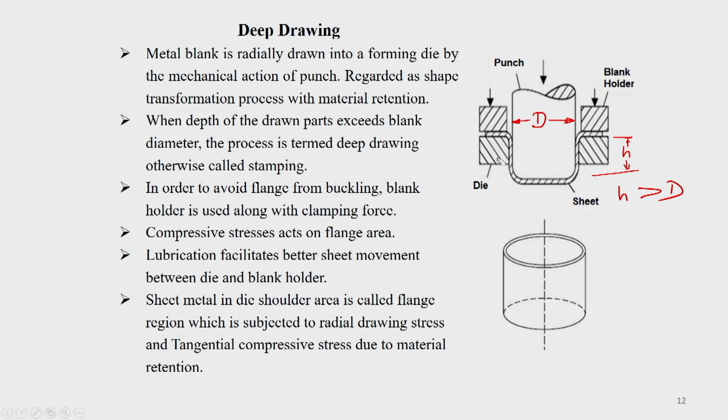Okay. So, in this case compressive stresses act here. When you are holding the sheet in this region, you will see that compressive forces are acting, and if you give some good lubrication and other things, it facilitates better sheet movement.